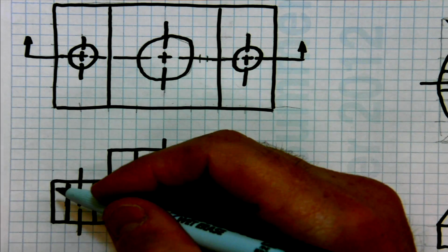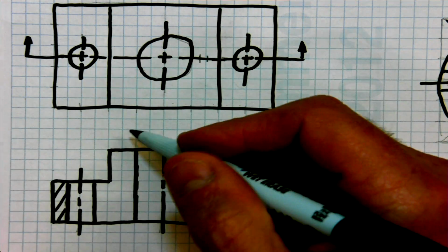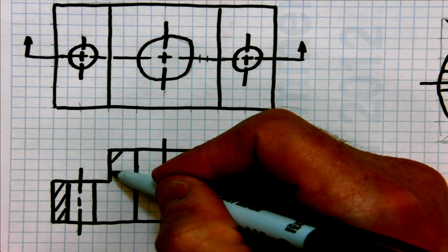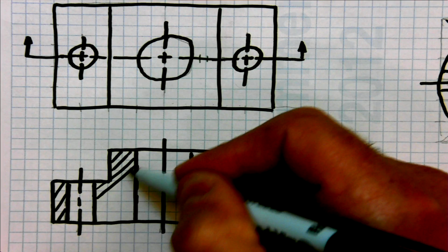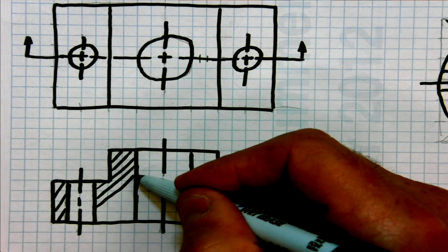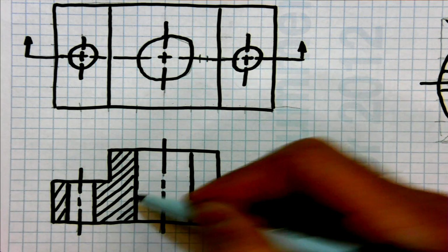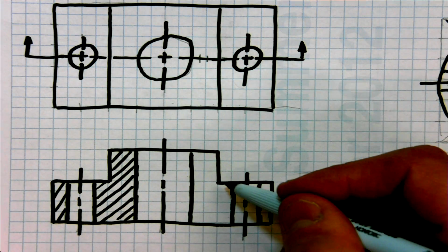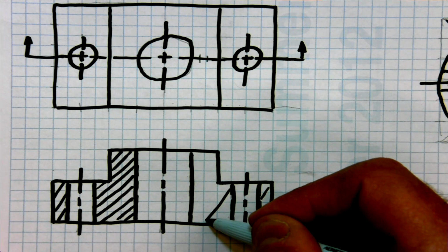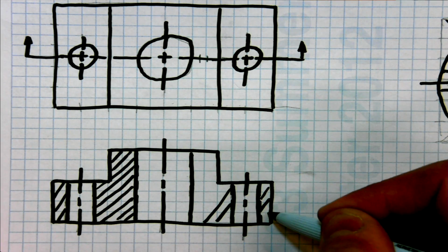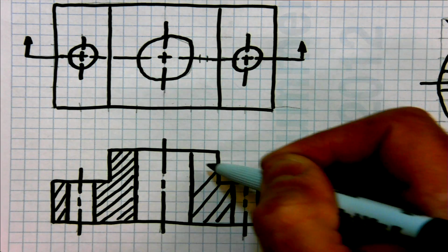So in this case, I'm going to start to cross-hatch this here, here, and there. Again, I'm going to try to keep the same angle, same direction. Be neat with it. Okay, I'm off here a little bit, I can see already. But where there's material, you don't fill it in, you don't make it solid. So let me try it over here and visualize this, trying to stay at the same angle. And one half of the object is cross-hatched, just the same as the other half of the object here.